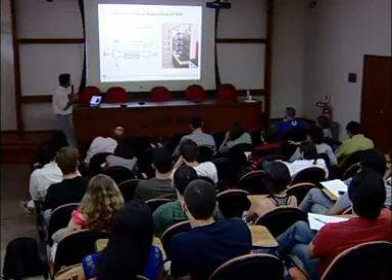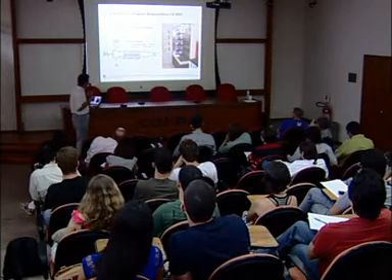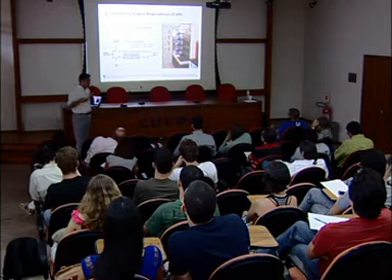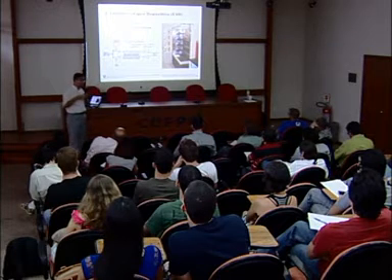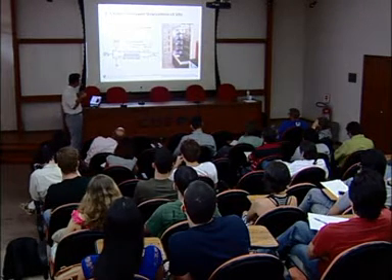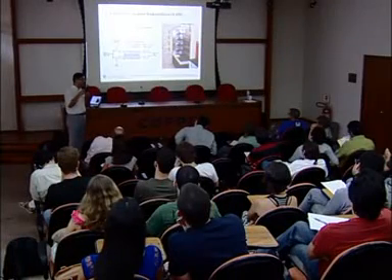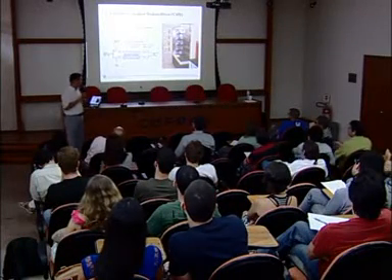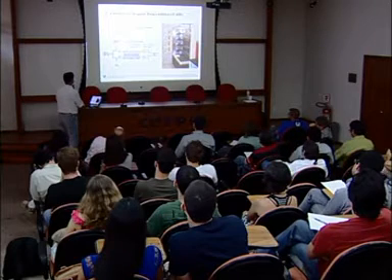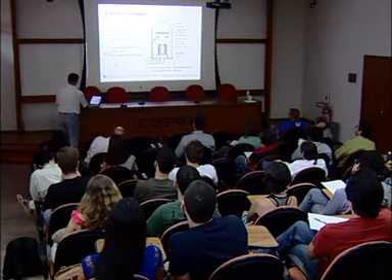In this vacuum, we can make a plasma, and the plasma will generate a lot of ions. Those ions will react on the surface, and the film can be very uniformly formed. So the key thing for chemical vapor deposition is to make a very uniform layer. Creation of a laminar flow on the surface, and making a very stable reaction on the surface, is very critical for chemical vapor deposition.